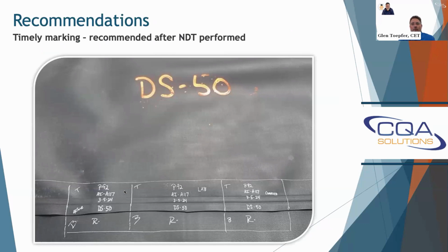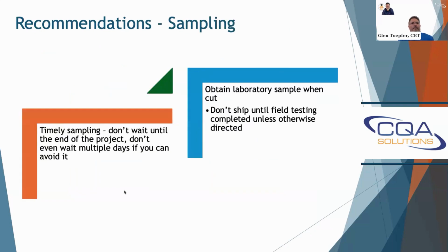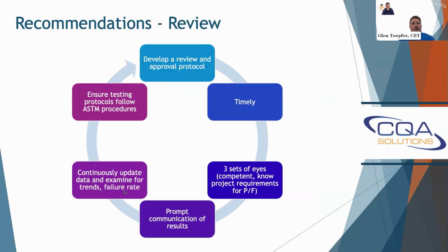Again, timely marking, wait until after non-destructive testing if you can. We talked about the timely sampling and timely shipping. For your review, this is often overlooked: develop a review and approval protocol, multiple people looking at it, timely review. It doesn't do anybody any good if you get results Friday morning and we don't find out about them until Saturday afternoon or Monday morning because you're on vacation. There has to be a protocol that addresses it and gets the information in the hands of people right away.